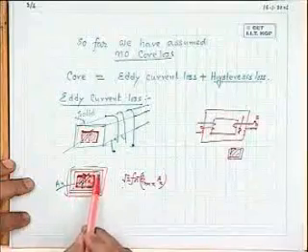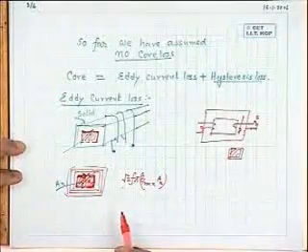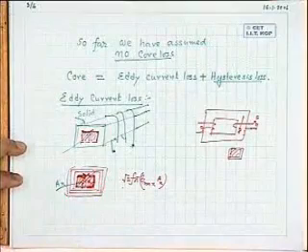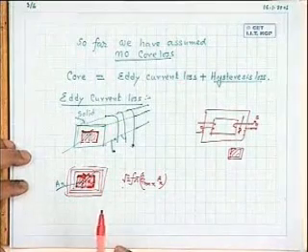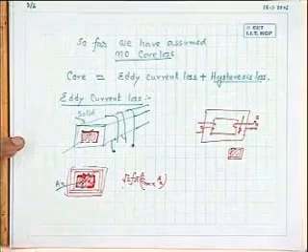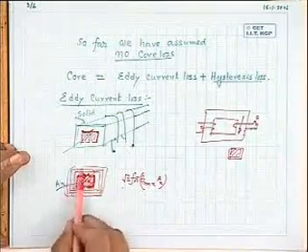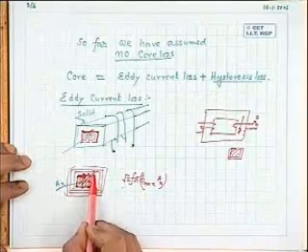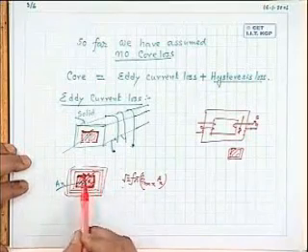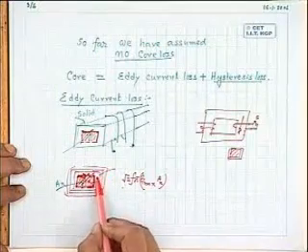And this is true for any path you consider. There will be several paths like that, and all the paths will have induced voltage, and all the paths are closed onto themselves already. So there will be some current inside the core of the material, and this will definitely produce some heating effect inside the core of the transformer.